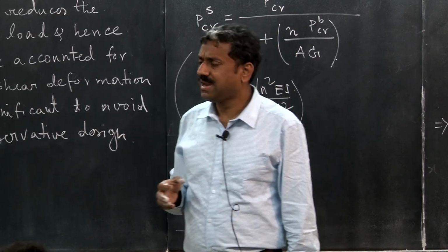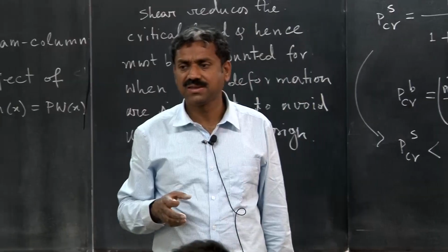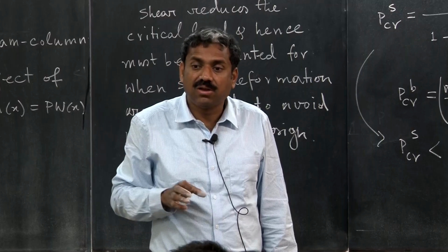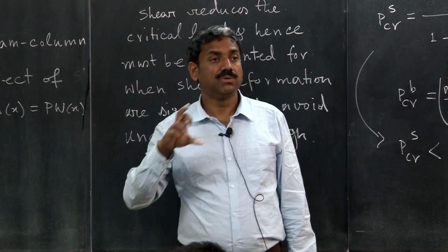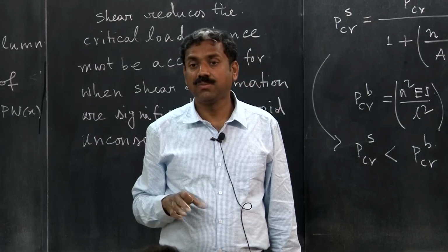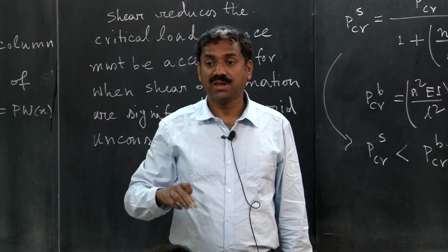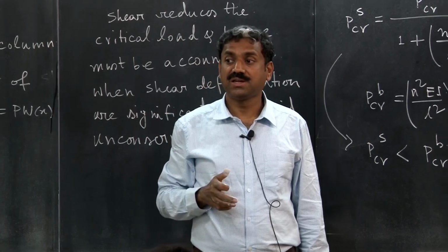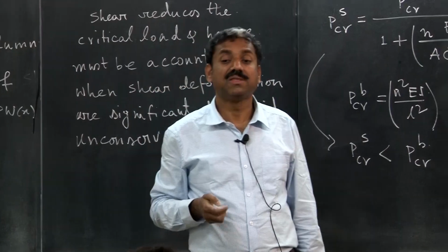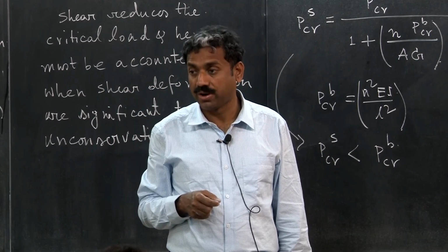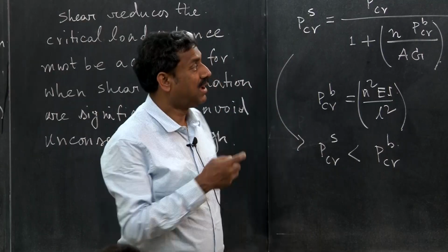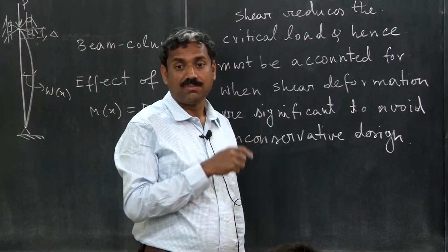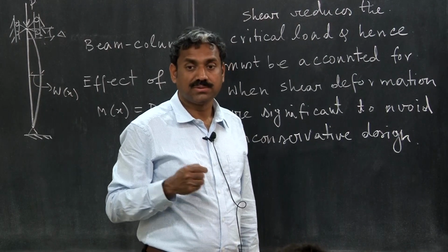However, later people realized that it is not that significant for many cases. Unnecessarily you do not need to consider the shear deformation, only if it is significant. It was particularly significant because we were using laminated composites. In laminated composites, you have a series of laminae glued together, and because they have low shear resistance, the shear deformation will be significant, and that is why refined shear deformation theories are important. Even the higher order shear deformation theory, when you include it in buckling, has had lots of studies.